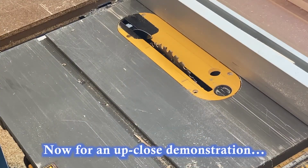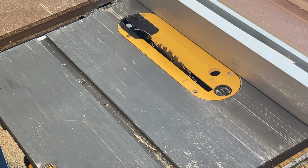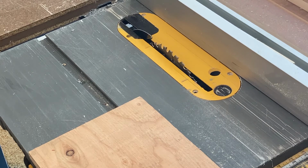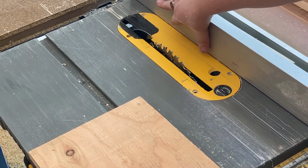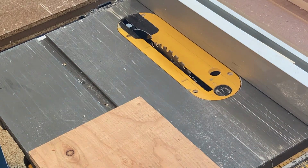So I just want to show you kind of over my shoulder here what I'm paying attention to when I'm using this tool. I've got a little scrap of plywood, which is the same thickness as the wood we're working with, so I don't have to change the blade or anything. But I just want you to be able to see what's happening here. 2.5 inches isn't too tiny. I personally am comfortable placing my hand here against the fence. If it gets much more narrow than that, people often will craft push sticks.